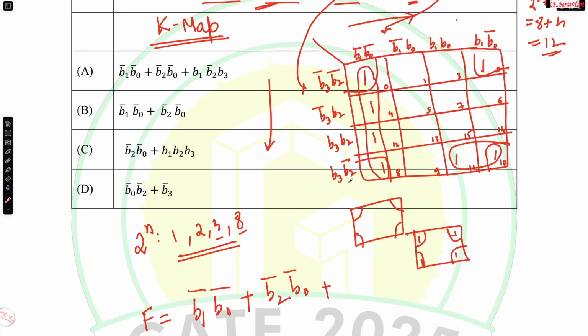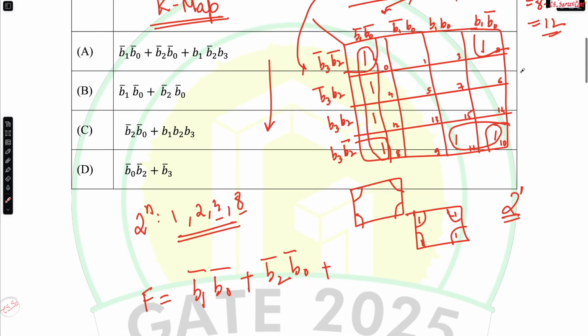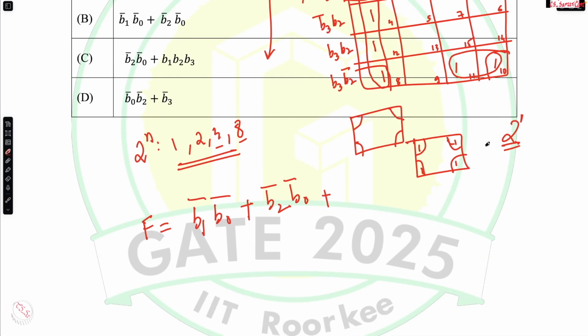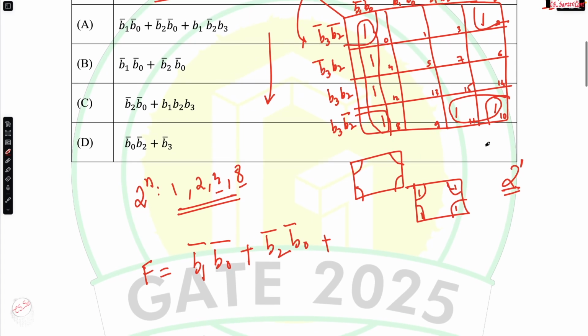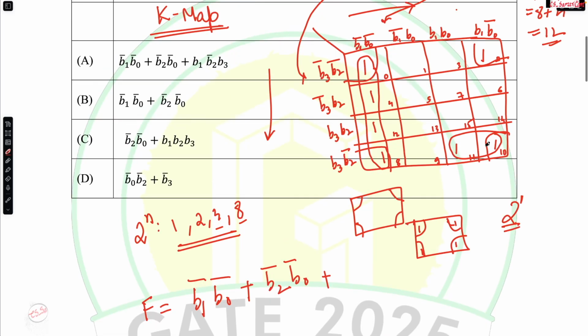Now, mind you, over here it is a grouping of only 2 terms, right? And for that 2 raised to the power of 1 is present. So this time, from the original 4 variables that are present inside of this expression, only a single variable is going to be removed, right? Be mindful of that, because if you are mindful of that, then you can catch silly mistakes that you sometimes commit, right? When this is being considered, this part is not changing at all, so we can directly write this part down over here.